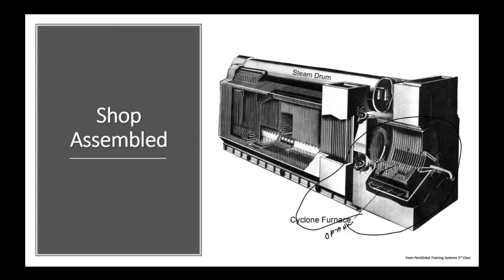Okay, do I want to burn coal that has a low ash fusion temperature? Then what I would do is use something called a cyclone furnace, which is different from a natural gas burner or an oil burner, right? So a very big option. This particular boiler has a superheater back here.